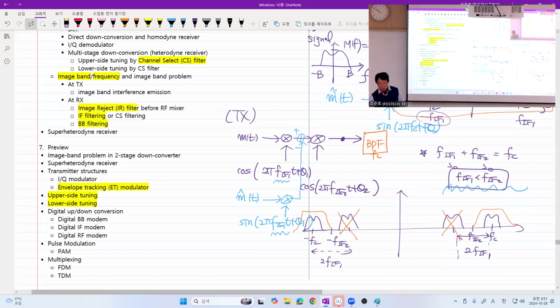Now, when you mix a real valued bandpass signal with a real valued sinusoidal signal, you have two separate signals on the positive frequency side and two signals in the negative frequency. And people named these signal components as what? As this signal and that signal. So this band is called upper side or higher side.